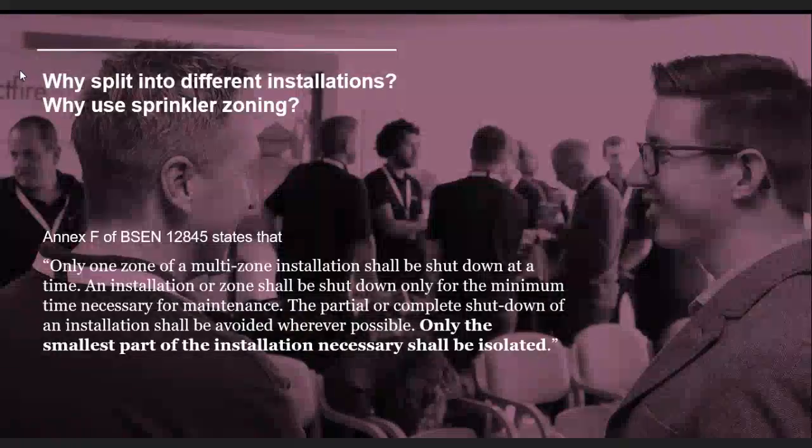That signal can be passed on to various other panels and systems to manage that, do some cause and effect with it, start putting the evacuation plan into action: opening doors, smoke vents, curtains, closing off maybe one side to say you've got to evacuate through these doors, not those doors, all based on where the activation has taken place. We can be quite clever with that these days. And obviously, the more zones you have, the more flow switches you have, the more information you've got to then bring forward.